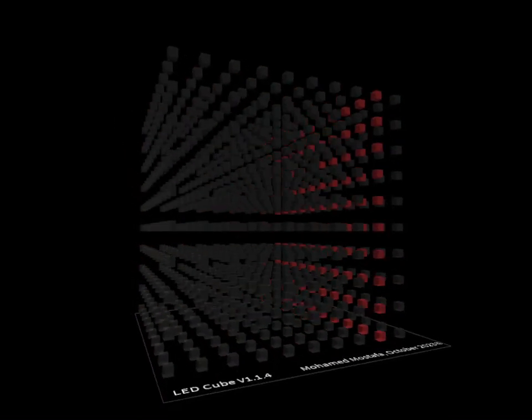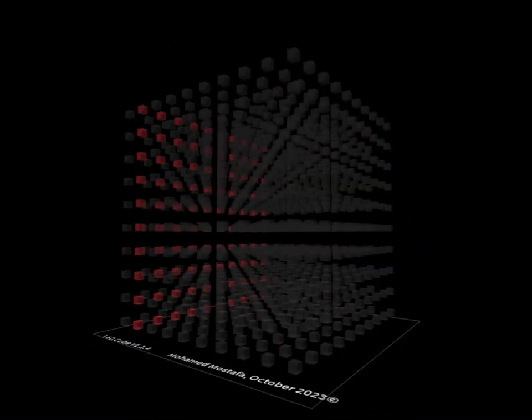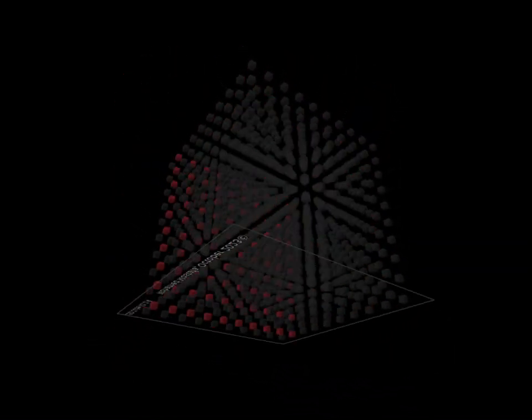A LED cube is like a LED screen, but it is special in that it has a third dimension, making it 3D. Think of it as many transparent low-resolution displays. In normal displays it is normal to try to stack the pixels as close as possible in order to make it look better, but in a cube one must be able to see through it, and more spacing between the pixels, actually voxels since it is in 3D, is needed. The spacing is a trade-off between how easy the layers behind it are seen, and voxel fidelity.